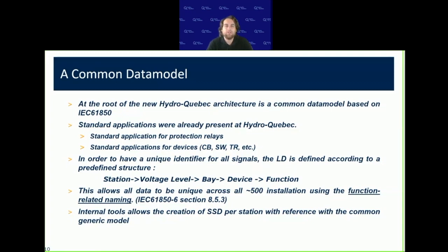So we decided to structure all this information based on the 61850 standard on the typical hierarchy of station, voltage level, bay, device, and then function, on a function-related naming basis. We'll see how this is important in a few moments.